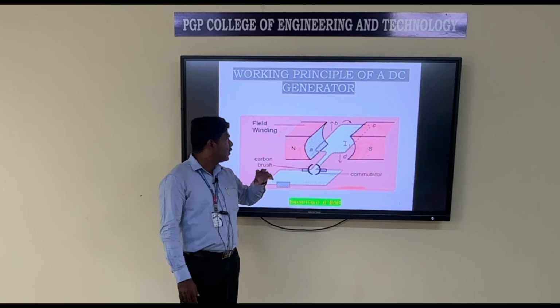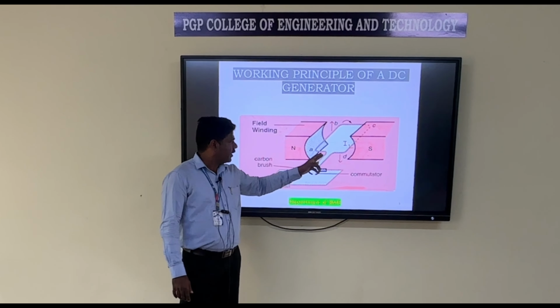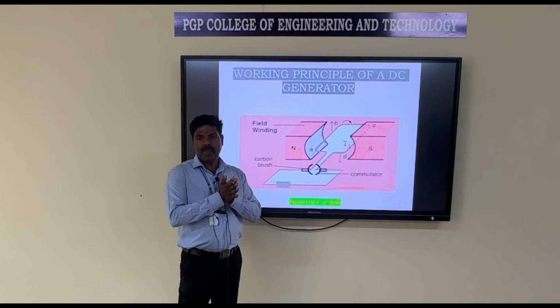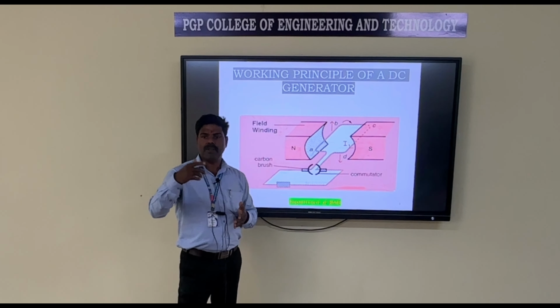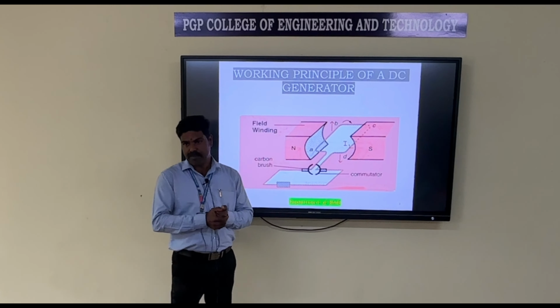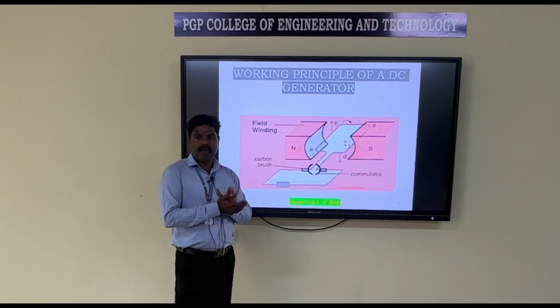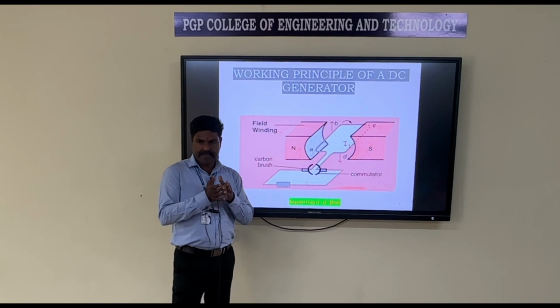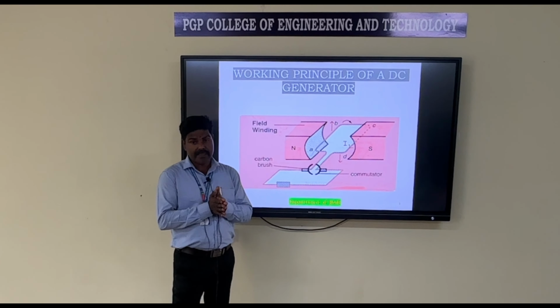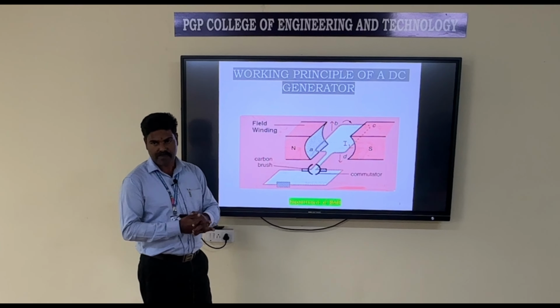That is the working principle used in DC motor. Here for the current carrying conductor, we are giving input energy as electrical energy, that is converted to mechanical energy. In that electrical energy, some supply voltage is there, that opposes the induced EMF. In DC motor, the generated EMF is otherwise known as back EMF.